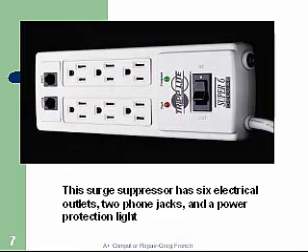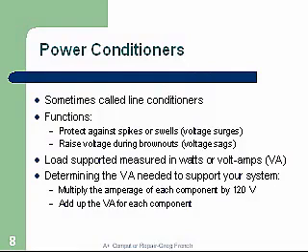Power conditioners, sometimes called line conditioners. Functions: protect against spikes, swells, and voltage surges. Raise voltages during brownouts. Load supported, measured in watts or volt amps. Voltage times amps gives you power, or watts.